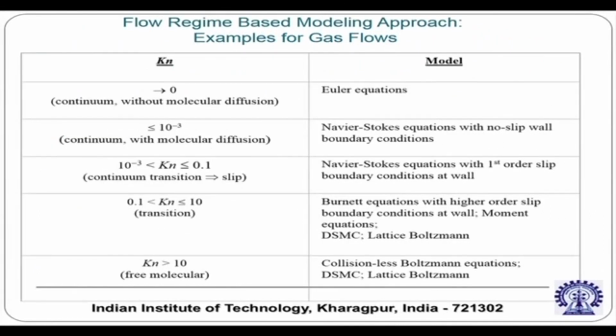molecular approach. So, for gas flows, for example, we have already discussed various Knudsen number based regimes, and this is just a demonstration of what your strategy for simulation should be based on the Knudsen number regime. Let us say you are asked to solve a problem of gas flow. Now what kind of simulation will you use? Based on the Knudsen number there is some guideline.